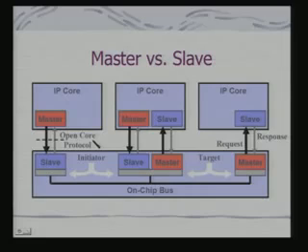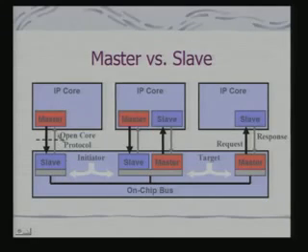The AMBA bus had a set of signal definitions as well as a set of transaction definitions. In fact, we had discussed for AHB bus transactions like burst mode transactions, transactions with security features, split transactions. All these transactions are defined as part of that bus definition itself. Here what we are trying to define is basically the protocol for these transactions. If you have standardized protocols, the IP cores would be compatible with these protocols.